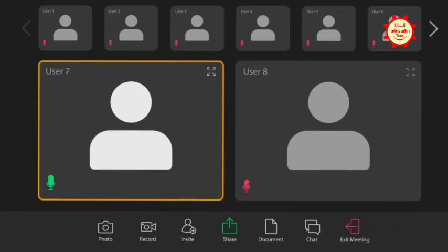Any other thing on this floating tube sheet we have to take care of in assembly or manufacturing, because you have manufacturing also? We have to focus on the gap between the bonnet flange and the backing ring, because mostly we see after assembly of the floating assembly, the bolt stud size shall be minimum 50 mm outside, for 2 threads. Then after that we have to consider a 20 mm gap.